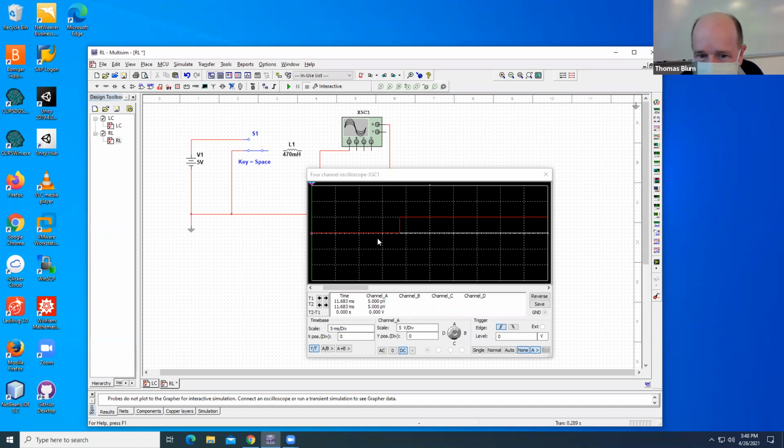If I say, what's the change? It's like a rate of change. The current didn't change by that much, but the rate of the change was infinite because it took no time to do it. The change in current will be delta I over delta T, the change in time, but there's almost no time here. It just went straight up. So that rate of change of current is very high, infinite right here. And that's what the inductor doesn't like. So that's what's going to change when we bring in the inductor.